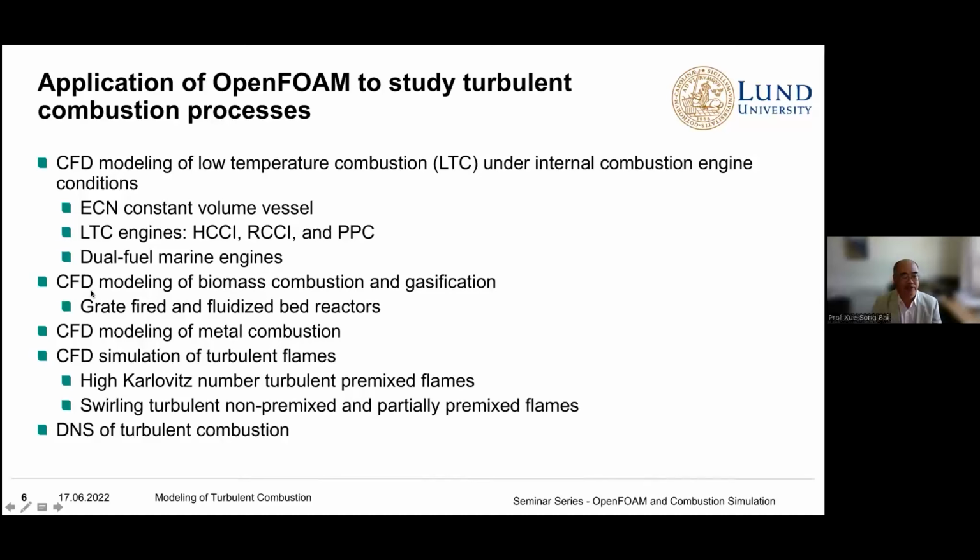Like I said, we also use OpenFOAM-based safety simulation to simulate biomass combustion and gasification processes, considering both grate fired and fluid bed fired systems. We also currently have ongoing work on metal combustion CFD modeling based on OpenFOAM.